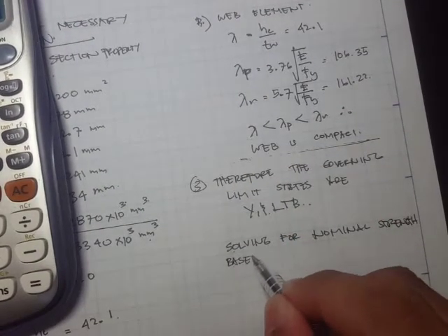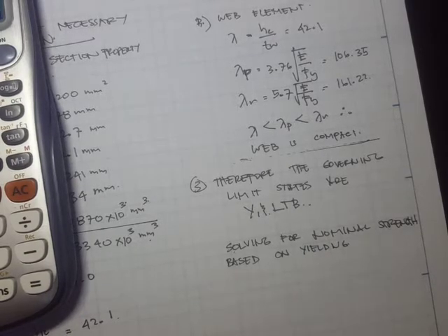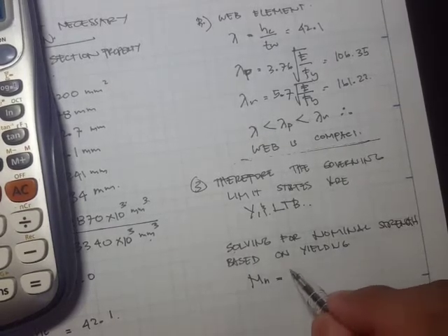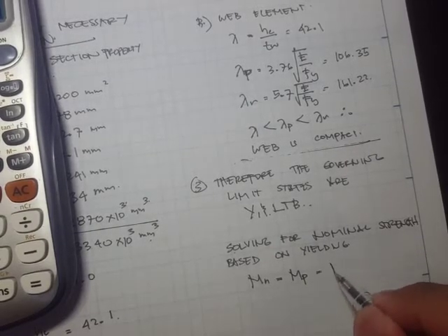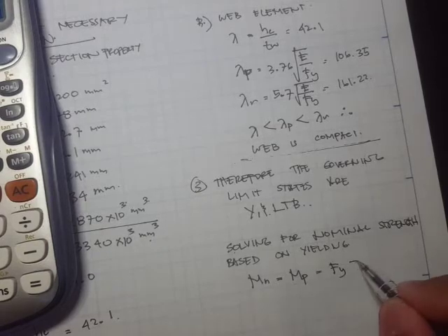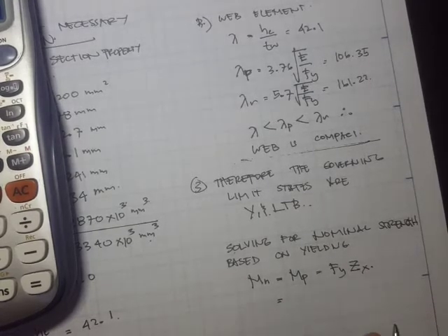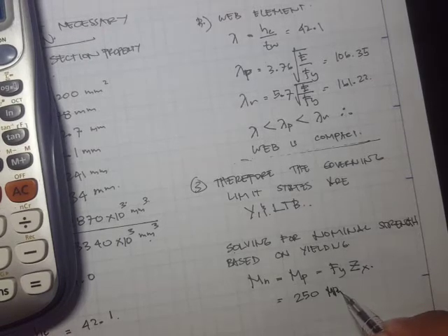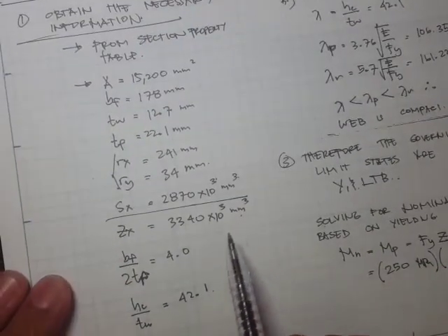Based on yielding. Okay, so our equation is just M sub n is equal to M sub p, the plastic moment capacity, which is equal to the yield strength of steel times the plastic section modulus. Okay, and this one is 250 megapascals, times our plastic section modulus,